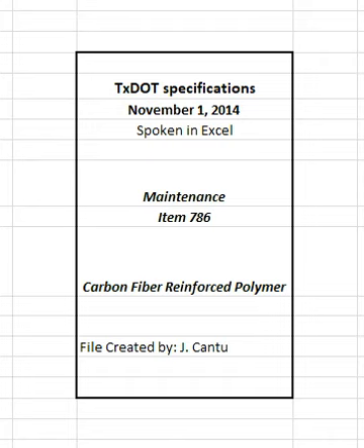3. Work methods. Obtain approval for all materials, qualifications, and methods of application a minimum of 10 days before beginning application. Provide a technical representative from a CFRP manufacturer for concrete member strengthening to provide on-site project support, to verify adequacy of surface preparation, and during the initial installation of the strengthening materials.